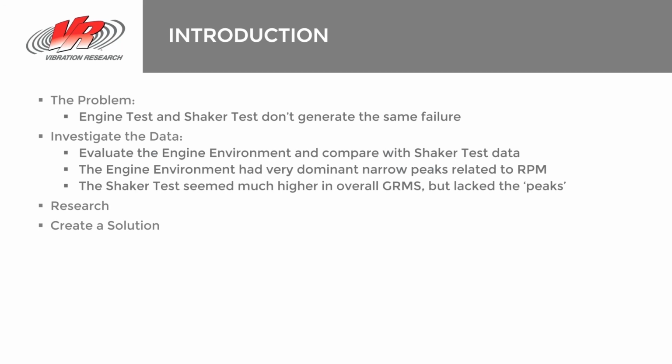And that's a problem. So we looked at the data and we dived into analysis, and the customer really dove into the analysis and figured out that, okay, we have to replicate this environment in a better way, and that should be done through a Sine-on-Random test rather than a pure random test.